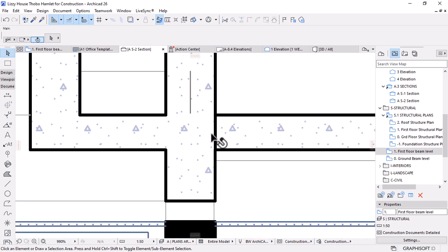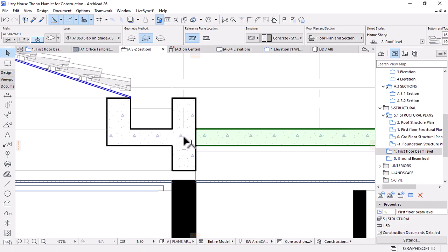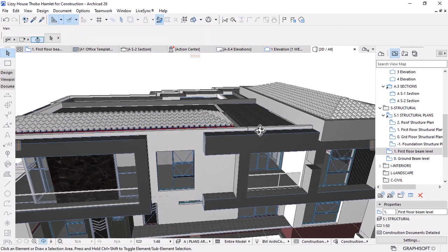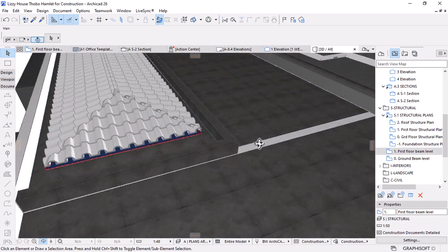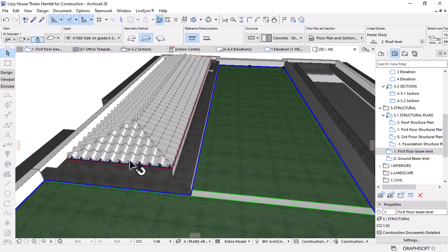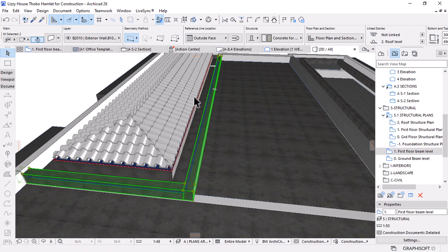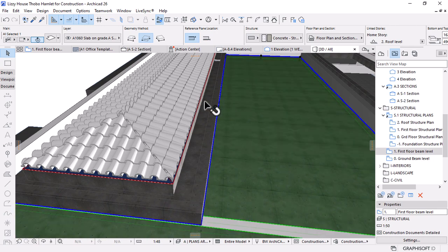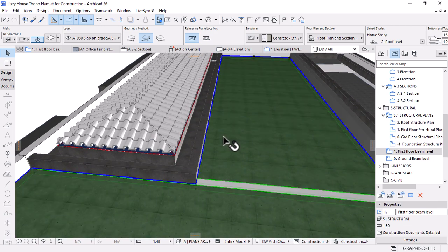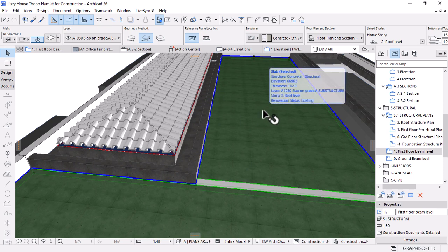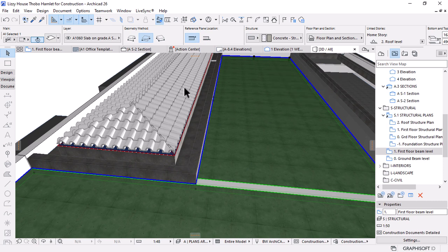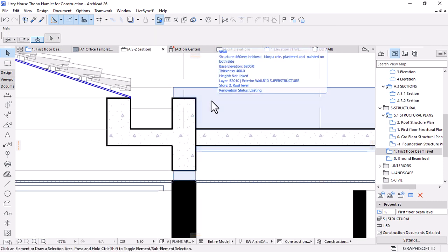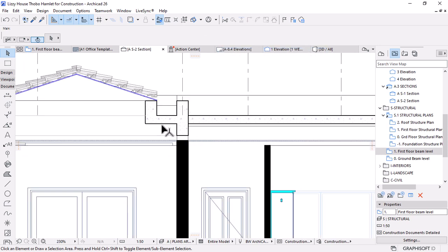The reason why we have a line here is because this is a roof slab, and then let me just show you that part. That's the area. This is the slab that I'm talking about, and that's the concrete that I was talking about. Can I have it continuous for this? My point is that you cannot cast at the same time this beam gutter and the roof slab. Maybe practicality, I'm trying to find a way of doing that. But for simplifying things, I would cast the beam separately and the slab separately.